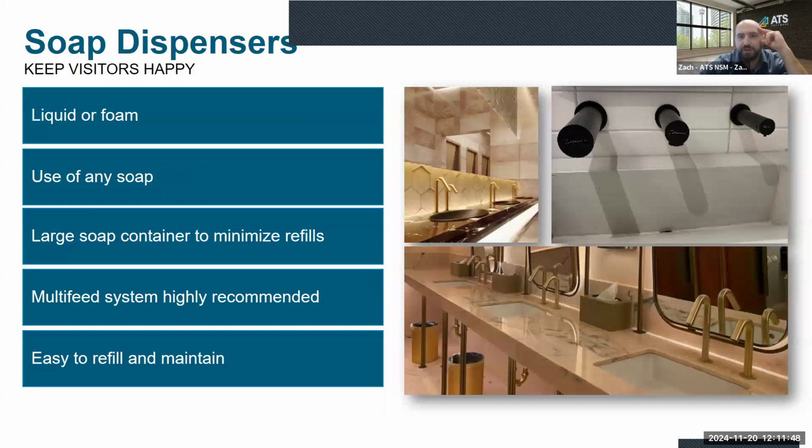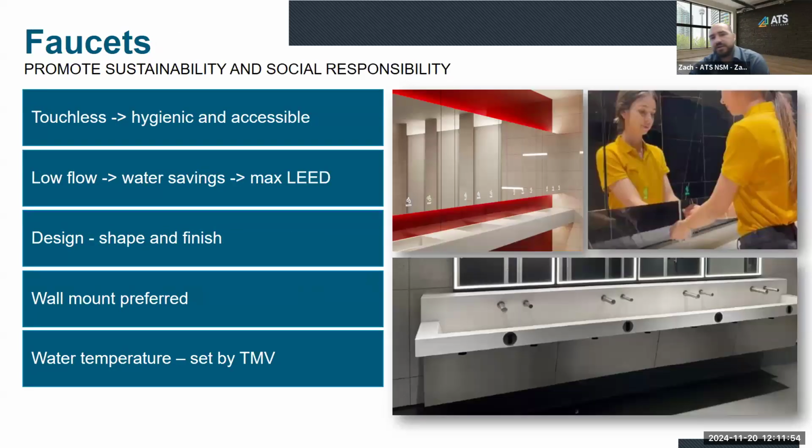Just a quick question there, on the last image of the last slide. On those types of wash fountain applications that you have there, where it's mounted on the backsplash, one of the comments I've heard is on installation and maintenance. Is there a minimum depth requirement to properly install those faucets and soap dispensers, so they can be easily installed and serviced well along the way?